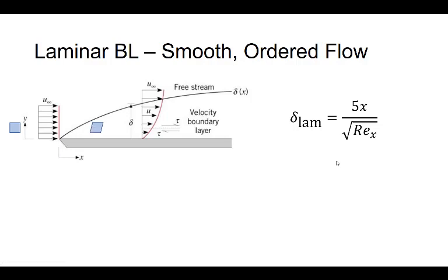Once the packet of fluid has moved into the boundary layer, the plate begins to slow the fluid down at its surface, such that the fluid molecules at the bottom of the square begin to flow slower than the fluid molecules at the top of the square. This causes the square to change its shape and move from a square into a parallelogram. The area of the square, however, is not changed, as mass must be conserved.